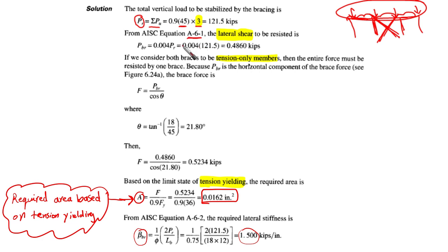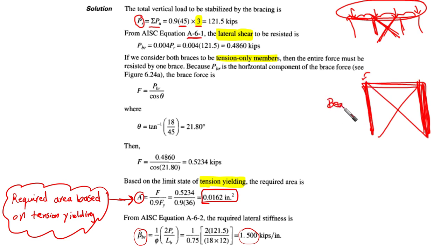So take care, even though we are talking about a frame, what we want to provide for it is stability for the columns. If we have moment on the column and axial forces, it is going to be treated as a column in this case.